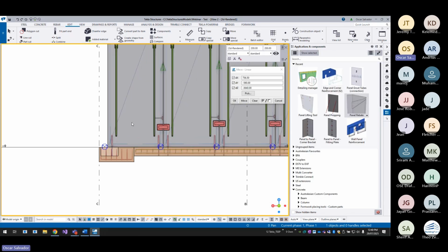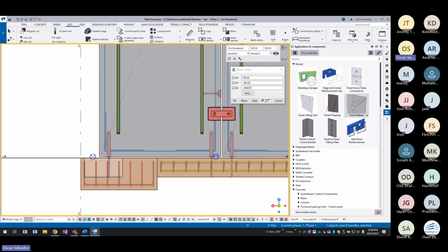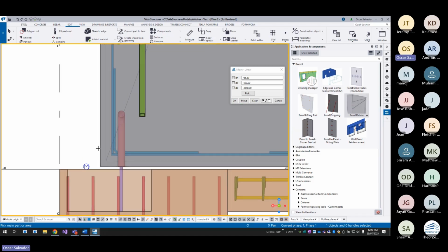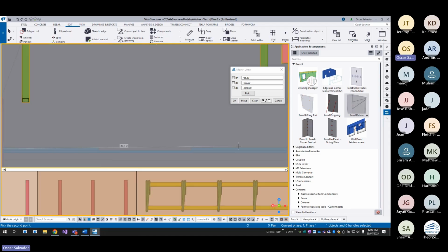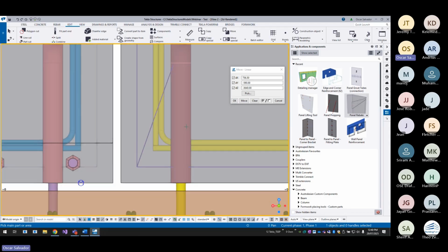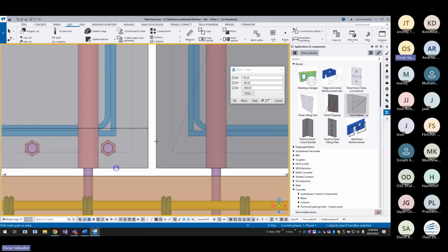So we have a 100 thick slab. So what I will do is I will click the panel and press the control key again. Click here and go up by 100. From there, perpendicular, click again, perpendicular,